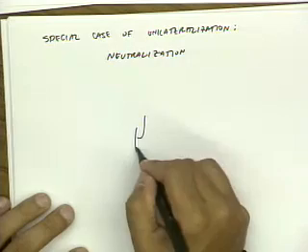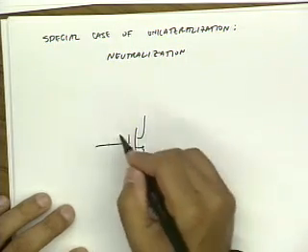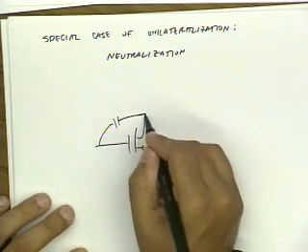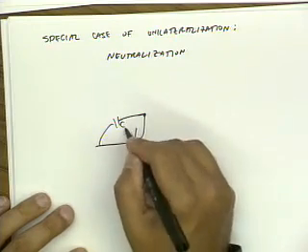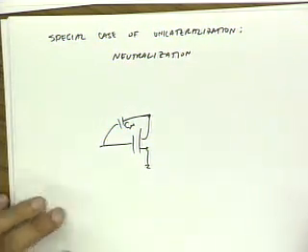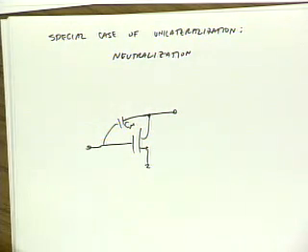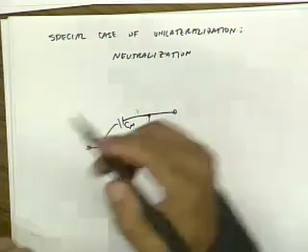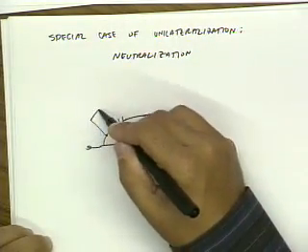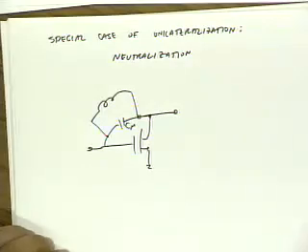So if I have a transistor, for instance, the only thing that's making this bilateral is C mu at low frequencies. How can I get rid of C mu? Yeah, I could just put an inductor in parallel here, right?